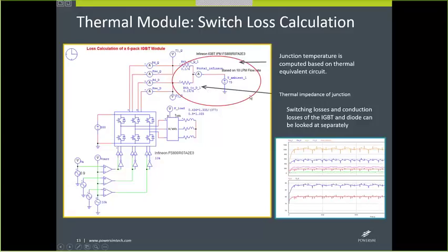If we wanted this to be a more realistic model, obviously we would have to put in a thermal impedance for the thermal interface and a thermal impedance for the heat sink. Maybe that heat sink needs a capacitance, a thermal capacity, so we'd put a capacitor into this network here. And then this ambient temperature probably won't stay constant, so we could put a changing heat source out here, a voltage source with an arbitrary waveform, and we could then look at a more realistic model of this heating up.